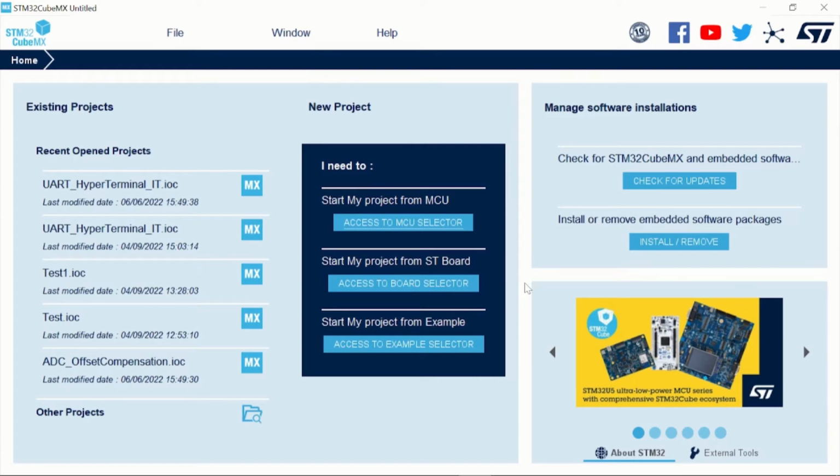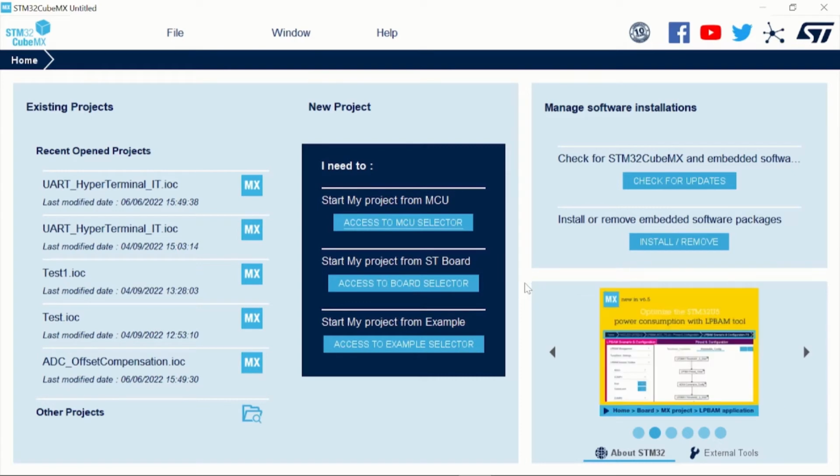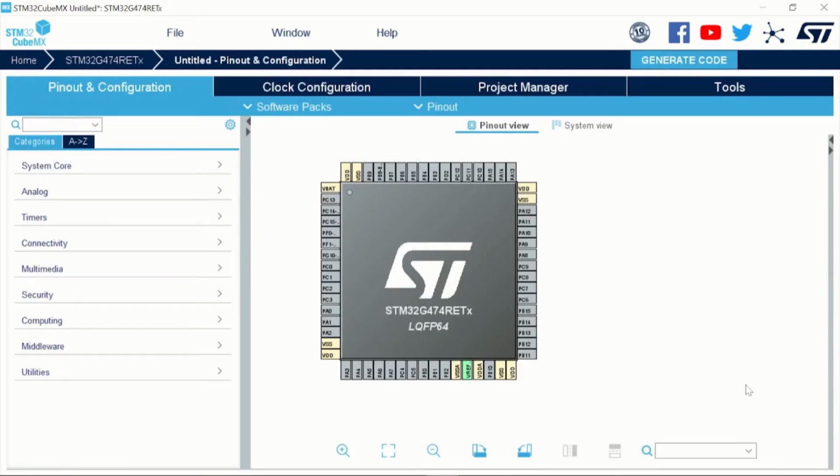Now we will be switching on to the key peripherals that are required within digital power applications. Digital power applications are very much timing critical. There are several analog signals that need to be sensed, and they will be processed within the microcontroller, and accordingly the right signal or the right PWM needs to be generated to switch on or off our MOSFETs. Along with that, in our hardware there are several comparators and op-amps to have various comparisons and sensing with appropriate gain.